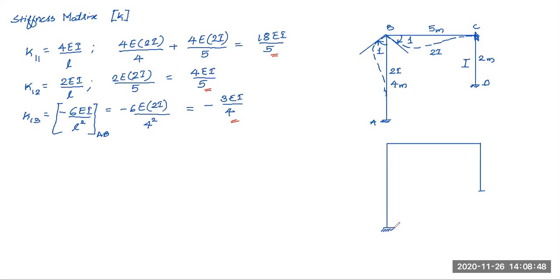You can proceed further if you are calculating. Here there should not be any displacement or rotation given in the first coordinate, so we'll restrain all the displacement in the first coordinate. That is, I don't want any rotation or translation in the first and third coordinates. This will be clockwise, right? Correct, clockwise. So I have to give a rotation in the direction of the coordinate. Here again I have to rotate two members for giving unit rotation in the second coordinate. These two are the rotations we have in the second coordinate.